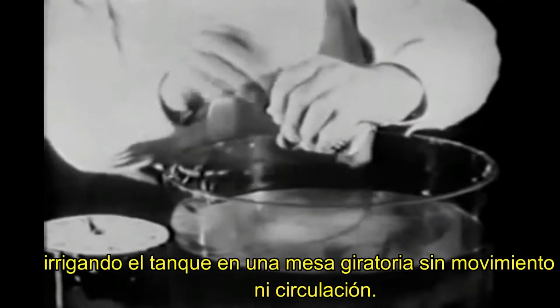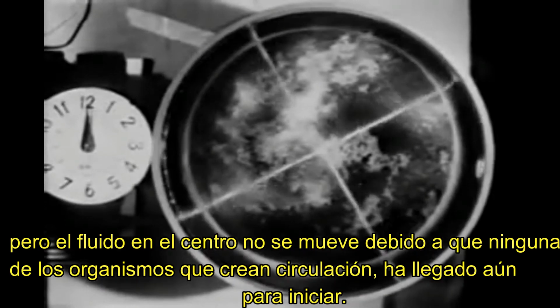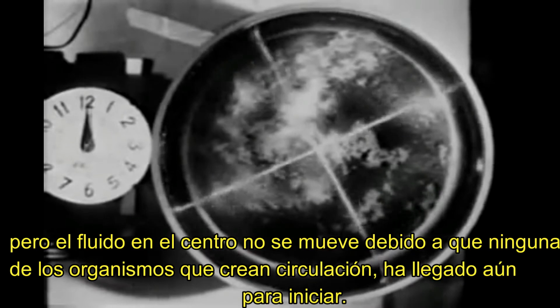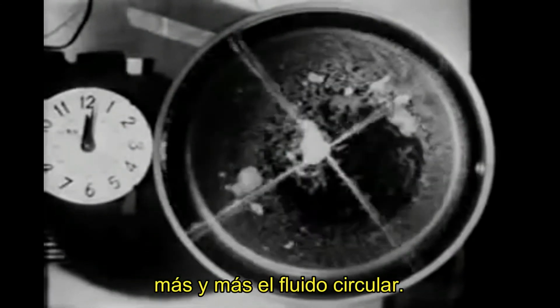Here again is the tank on the turntable, with no motion and with no circulation. Now the turntable has started, but the fluid in the middle doesn't move because none of the agencies which create circulation have yet come into play there. Next to the wall, however, the fluid does circulate because of viscous stresses. These viscous forces gradually diffuse outwards from the wall, and more of the fluid circulates.